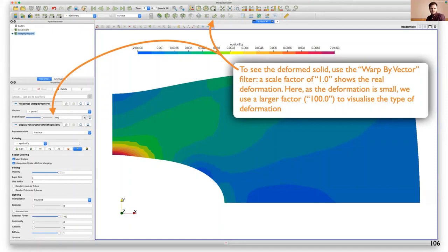So here's another question. Can a moving distributed load be modeled? There are a number of boundary conditions available. Is there a moving distributed load? I'm not sure if one is implemented. I know you could use Groovy to modify one of the existing load boundary conditions, though it wouldn't be that difficult to write your own boundary condition. So you can always contact me afterwards, or we can do it by just posting on the forum, and we can discuss it there. But you could use Groovy. GroovyBC will let you do it as well.